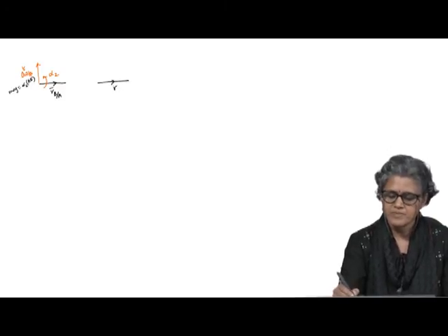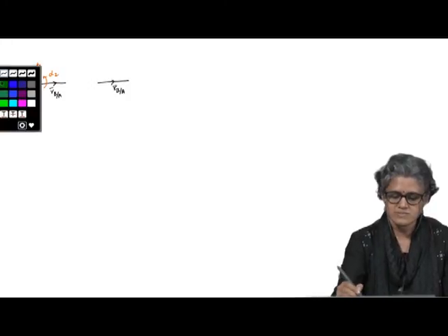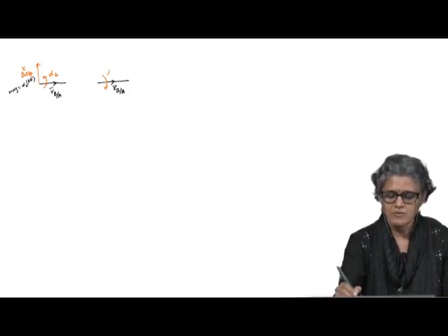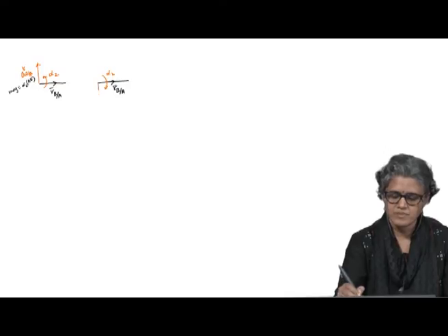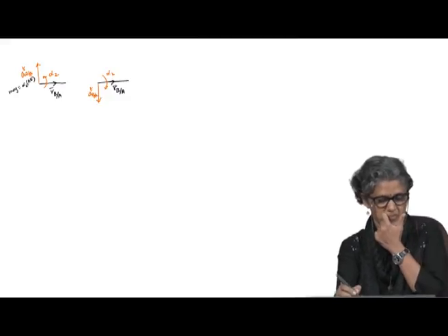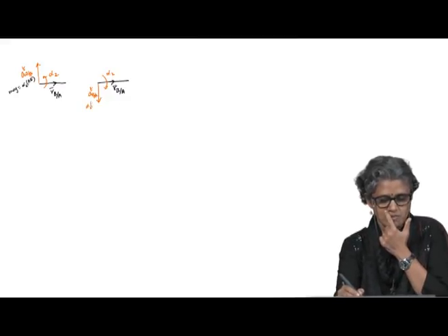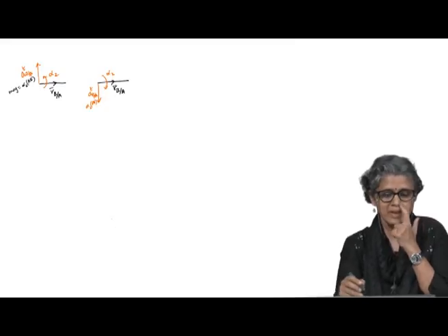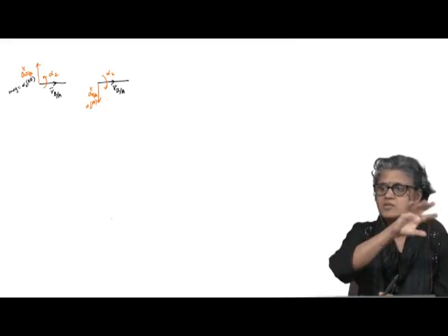Here, if this is the vector and my alpha_2 is clockwise, then this would be my tangential acceleration component, alpha_2 into AB. Same magnitude, different direction depending on the direction of alpha_2.